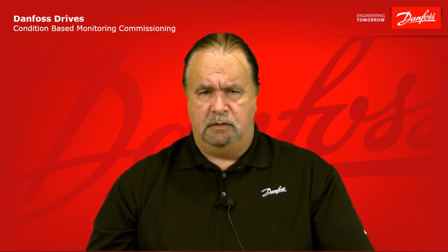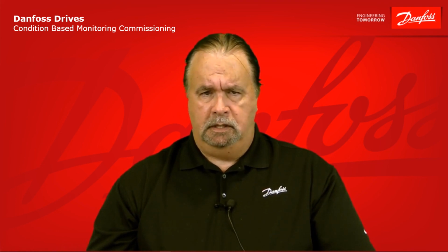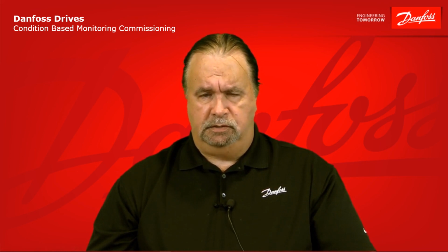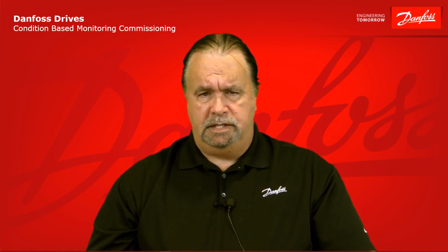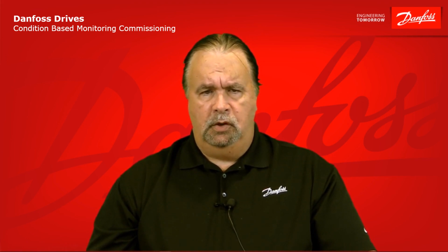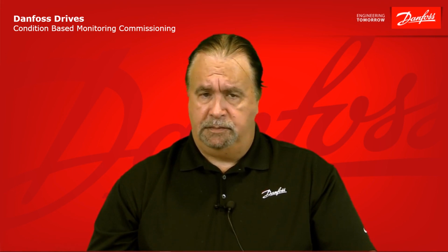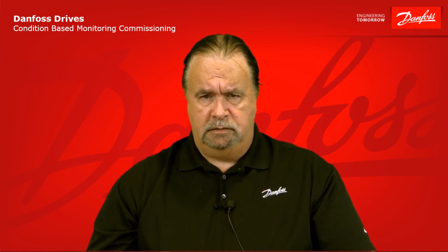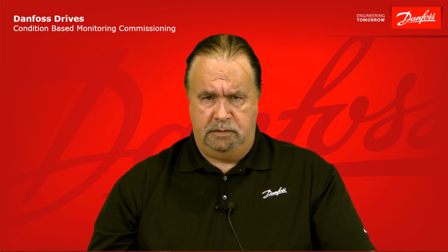The system focuses on the motor stator conditions and monitors change over time as the installation ages. Vibration monitoring is another key tenet in the system. We can quickly detect many changes such as loose mounting connections, bearing failures, and overall wear and tear. Load envelope monitoring provides us with a way to maximize efficiency and process optimization. We can schedule maintenance actions rather than respond to emergency failures.